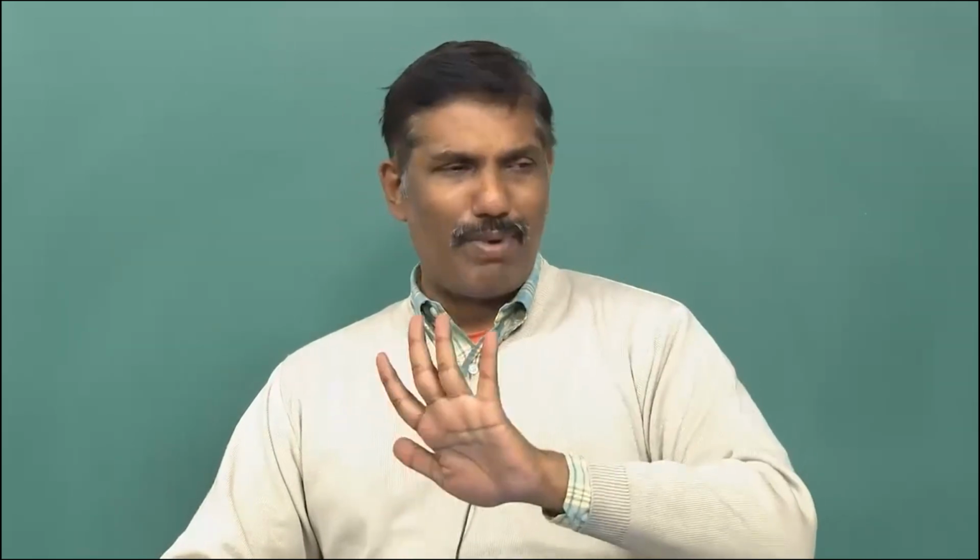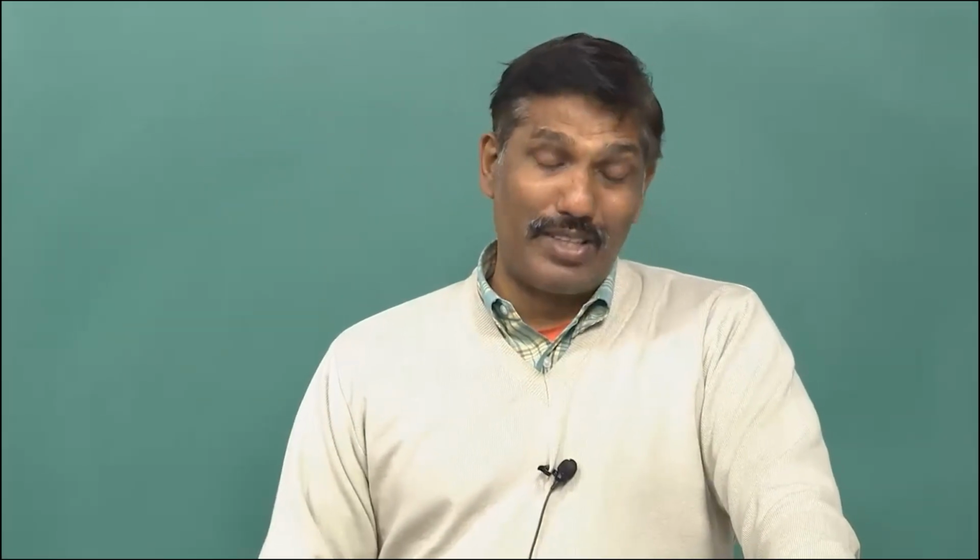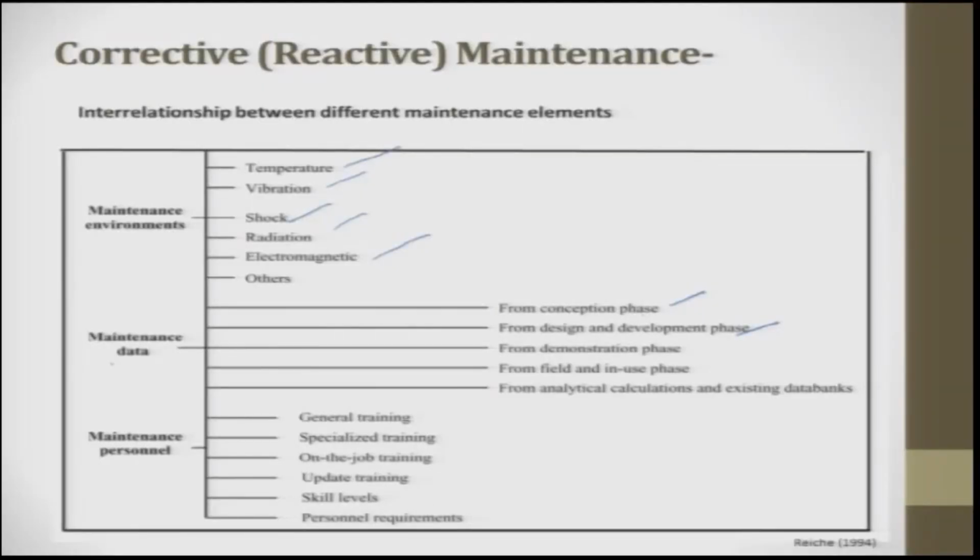When you put screws exactly on the spot or on the eyesight where it is visible, that is going to make the entire product look a little uglier. So, you have to have a trade off in the design stage itself about where to have these screws and bolts such that they can be fastened. The other way around is in the design stage itself you say, I hate these screws and bolts, let us have a press fit, shrink fit, done.